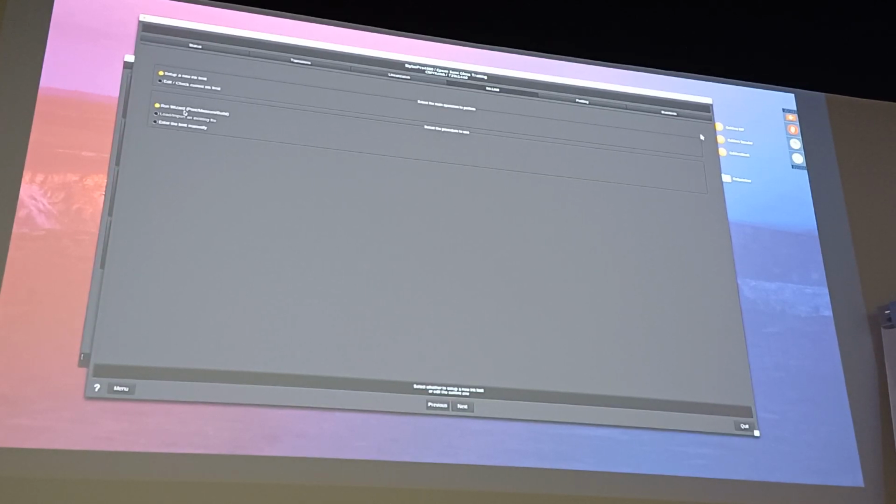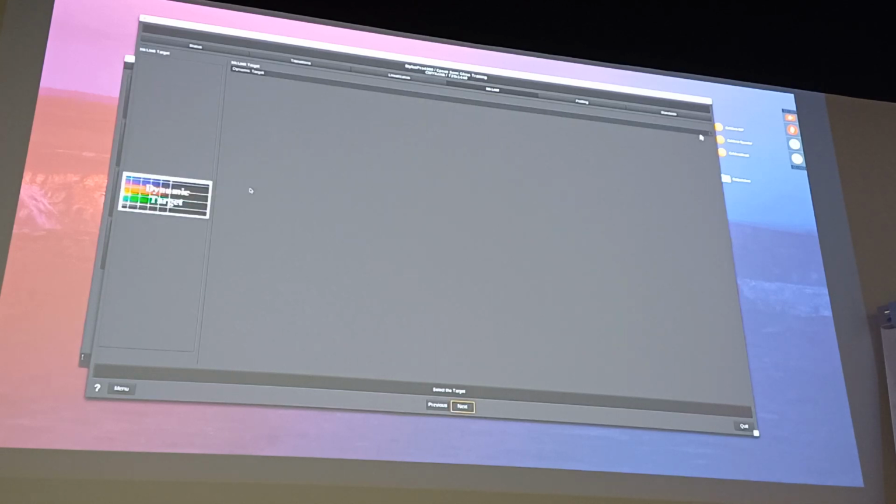So to do so, we will set up a new ink limit, and once again we will run the wizard. Here it is said that you will print, measure and build, but this is actually wrong. You will just print and build. There is no measurement required for this step. You will only take a look at the target with your eyes. You won't measure it with any spectrophotometer.